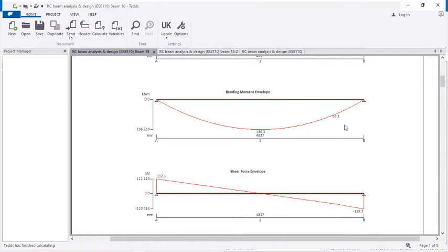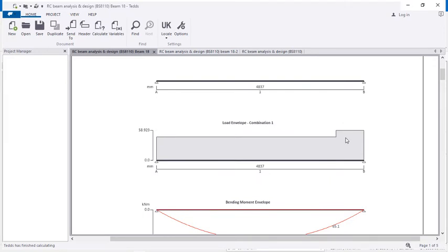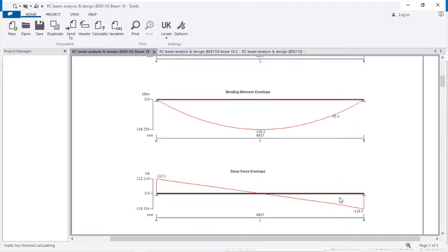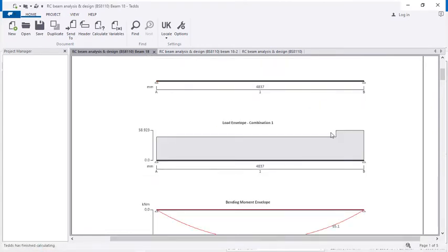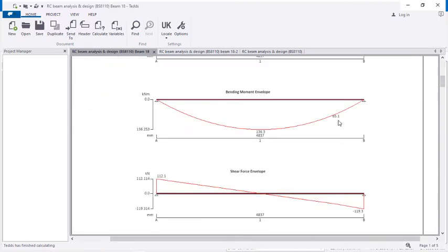And you can see the bending moment that is giving me that at this point, as a result of this load, I have this bending moment here up to this point, and this is the maximum bending moment, 136.3 for that beam. That is what I'm on. Now in this case, if you see, I've modeled that there's no point load.